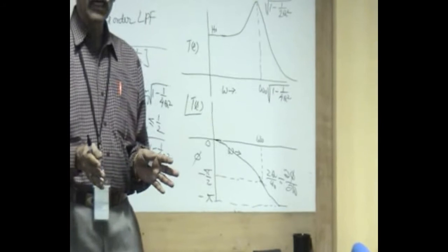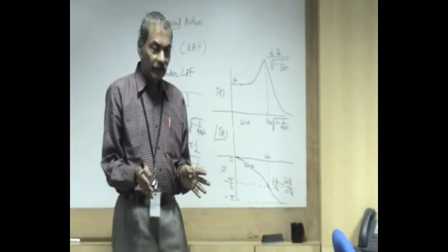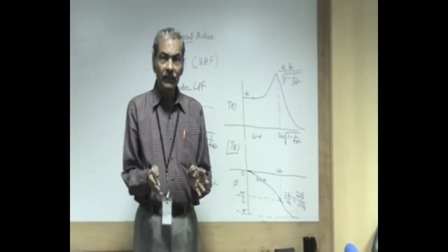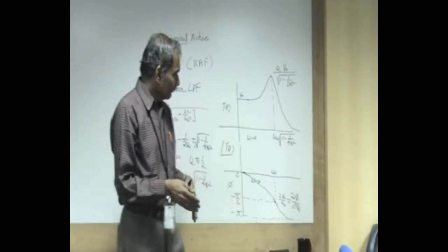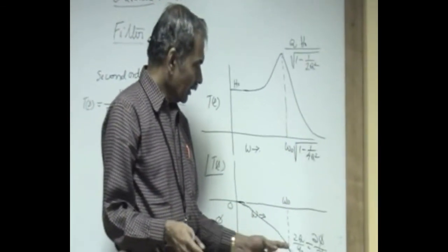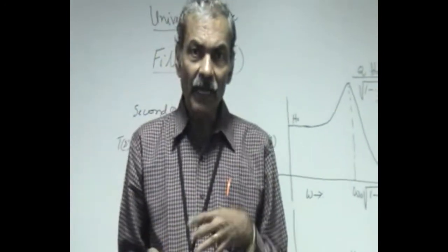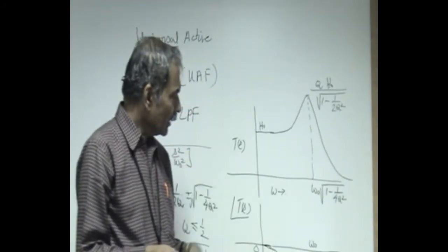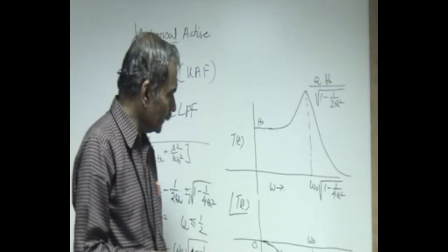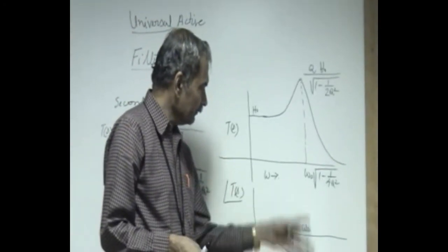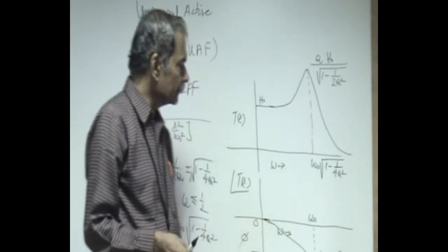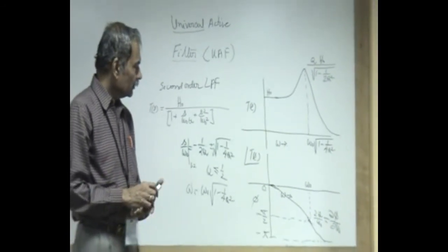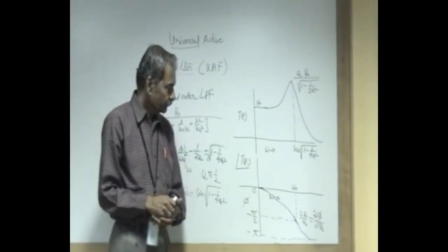And that is why phase detectors are used for tuning filters. Because the phase detector output is very sensitive to variation in frequency. And therefore, you have to use a parameter which varies the most, and that conveniently occurs around omega naught, the pole frequency of the system. Therefore we can tune most of the filters by using this information about phase. We'll later see how a phase detector can be used for tuning in self-tuned filters or phase lock loops.